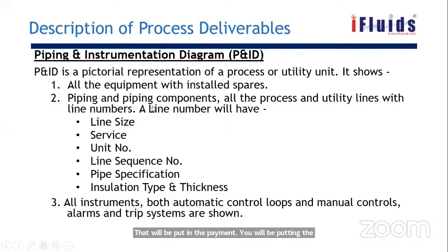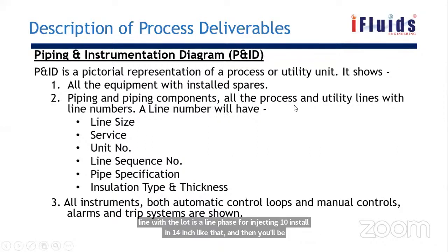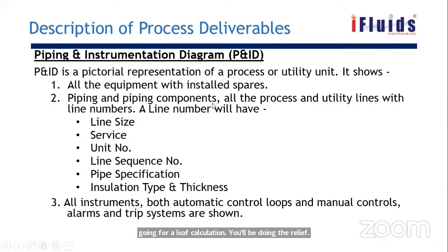And then you will be going for a relief valve calculation. You will be putting the relief valve size, and that will be shown in the P&ID. And what is the service in the particular line, and what is the unit number? There will be multiple units.